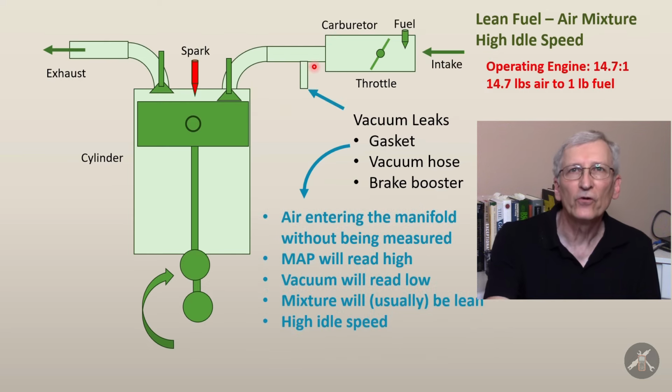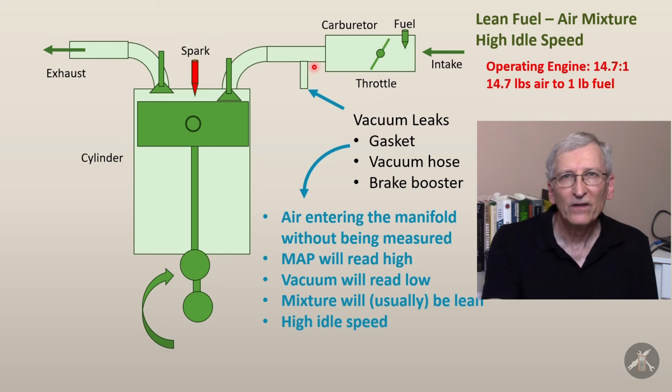Now, for those of you who are still running carbureted cars, a carburetor's really nice. A carburetor's a very sophisticated analog computer that feeds fuel in a mass-air ratio. Pretty cool. The problem is that you have the physics of how fuel moves and how air moves, and they get very sophisticated with air bleeds and jets and multiple air bleeds and multiple venturis. I'm not going to go into designing carburetors right now, but carburetors are great. It's a very sophisticated instrument, and they're really pretty nice, but they can't do as much as electronic fuel control can do.